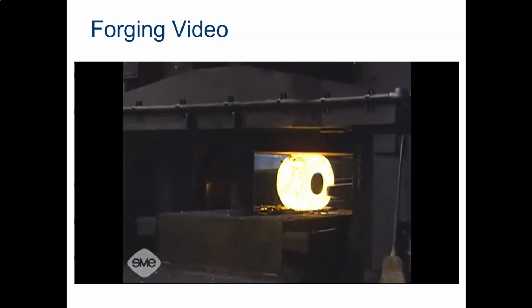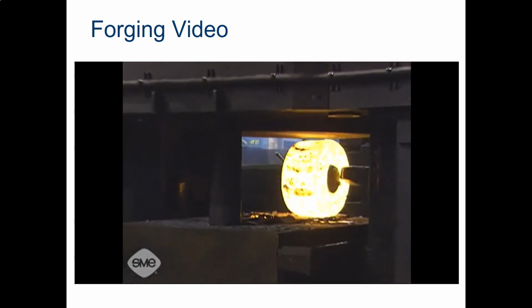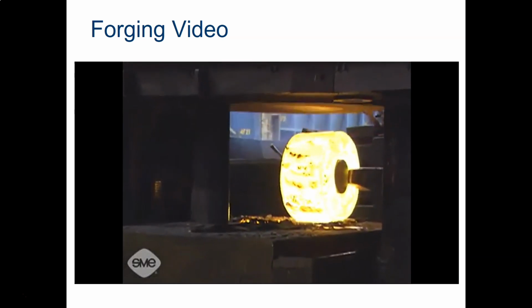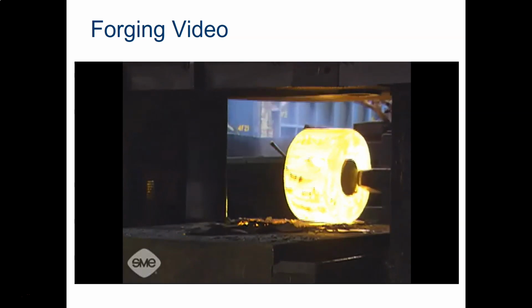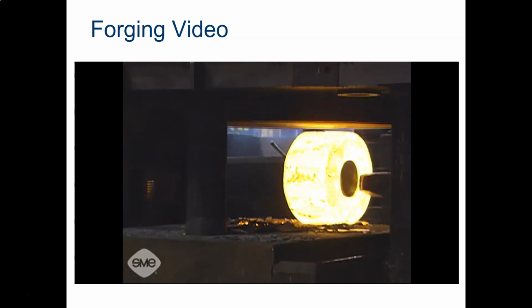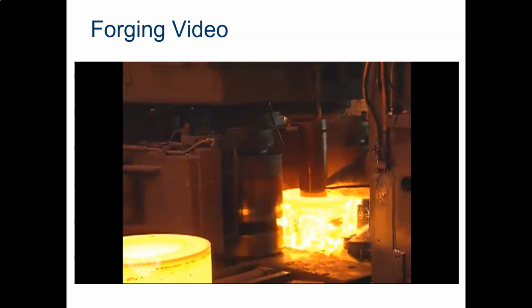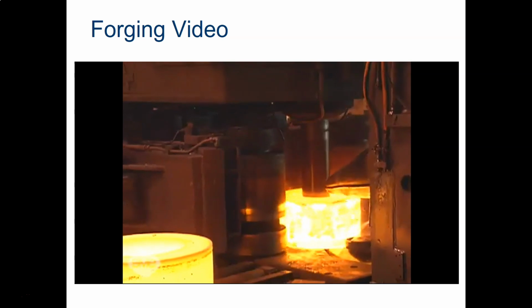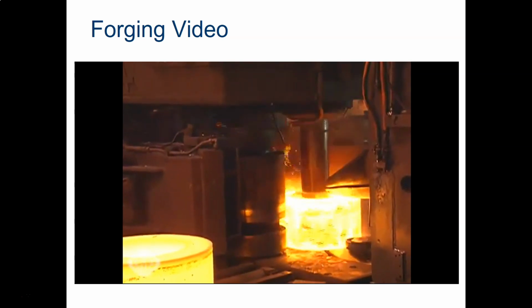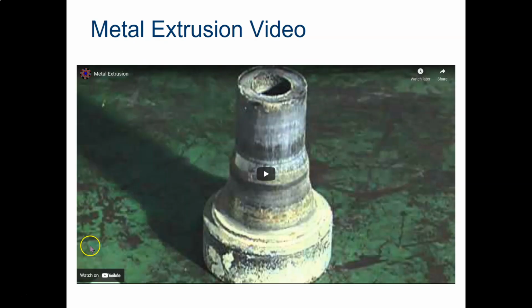It is utilized today to reduce the cross-section, improve the metallurgical microstructure, provide directional grain flow, and eliminate porosity of cast ingot in fabricating wrought mill forms, and to form discrete parts to near net shape from these wrought mill forms, further refining microstructure and directional grain flow. And also this video on metal extrusion.